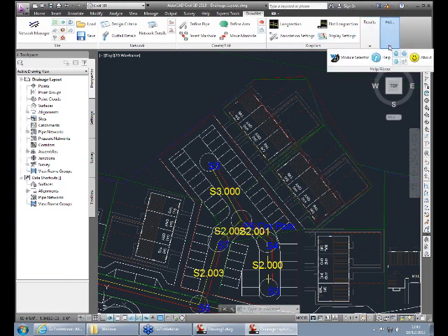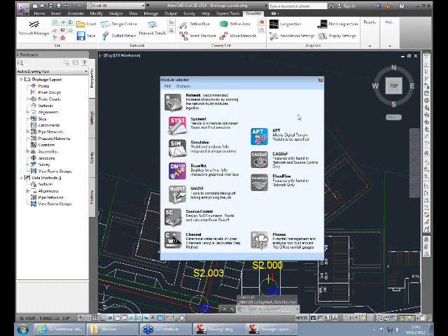One of the key things we've added in version 2013 of the software is a new module selector. Many of you will be familiar with the previous satellite diagram and how we used it in version 12 of the software to navigate between the different modules and which ones you had open or closed. In here we've tried to simplify it by basically you select the module which you wish to have turned on and it will highlight. If you don't want it on, it greys out. So currently we're working in DrawNet CAD, so we have System 1 for the modified rational method and optimize engine, APT to pick up the cover levels from the digital terrain model, and DrawNet for the graphical interface.